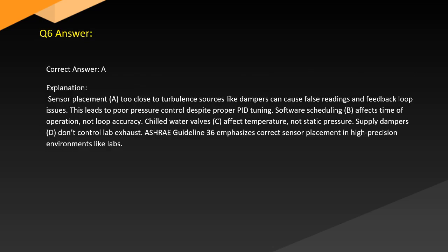Answer. Correct answer: A. Explanation. Sensor placement too close to turbulent sources like dampers can cause false readings and feedback loop issues. This leads to poor pressure control despite proper PID tuning.